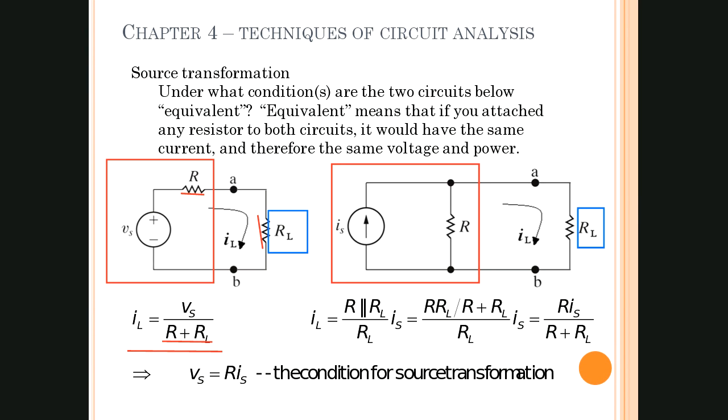Let me give me a second while I do another shape. And I will pick purple. So again, we'd have to use these two resistors, if you guys can see this right there. Get the equivalent resistance, and then we can do a current divider equation to give me what the current through RL would be. Again, current divider just means that I am proportioning the current between that network, and a certain proportion of it will go to RL, and a certain proportion will go through R.